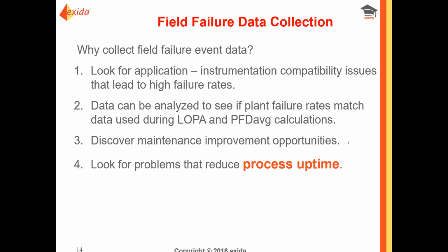Number two, data can be analyzed to see if plant failure rates match the data used during LOPA and PFD calculations. Why would you do that? I'm not going to do these calculations over again, you might be thinking. Well, what if the assumptions you made, the databases you were using, do not match the reality of your site?